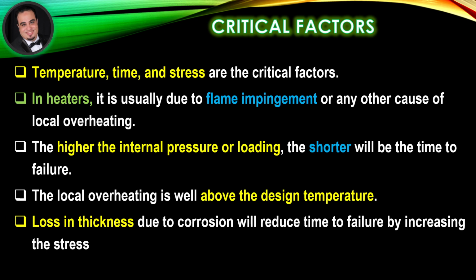In heaters, it is usually due to flame impingement or any other cause of local overheating. The higher the internal pressure or loading, the shorter will be the time to failure. The local overheating is well above the design temperature. Loss in thickness due to corrosion will reduce time to failure by increasing the stress.